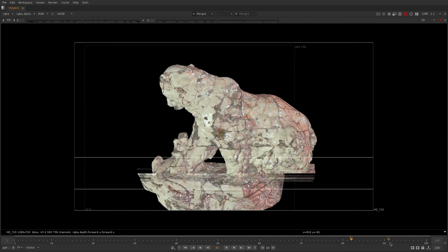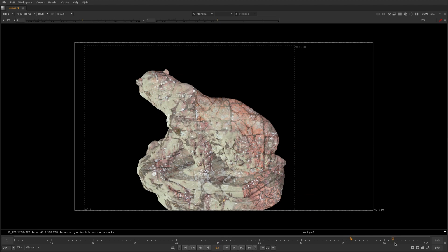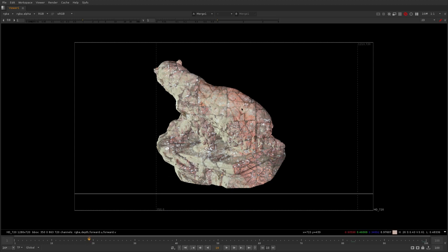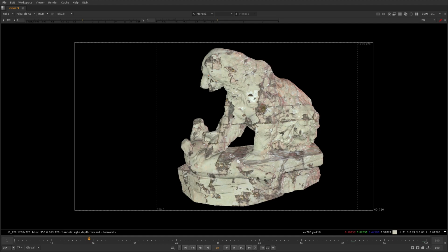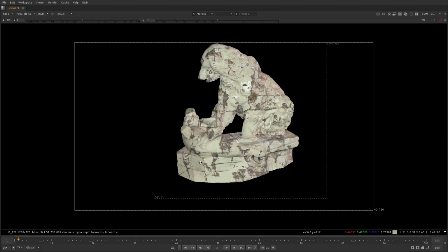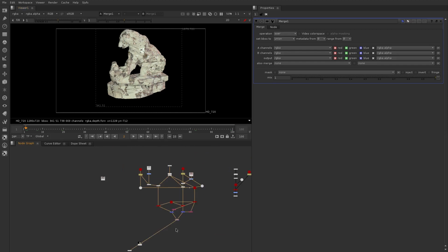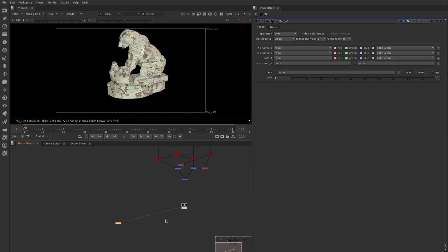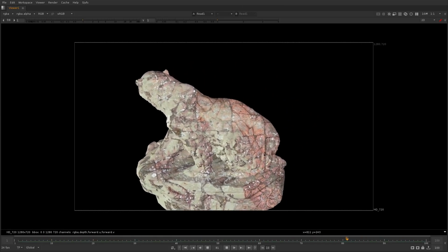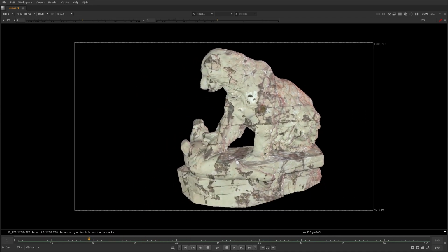So the idea is to use a light that we parent to the camera that we need to project from, do a diffuse render from that camera, and then use that mask to isolate the data that we need from the texture being projected onto the geometry. And this will work perfectly with any complex geometry. And the last thing I wanted to talk about quickly, so let's take a look again. We're only using two lights here, and we've used the red and blue channels.